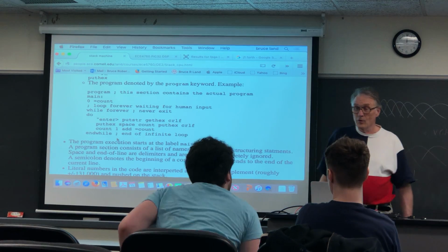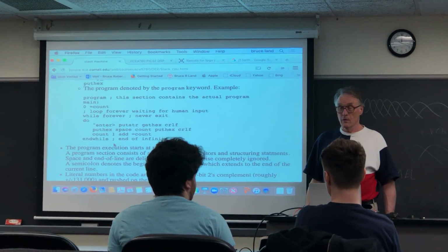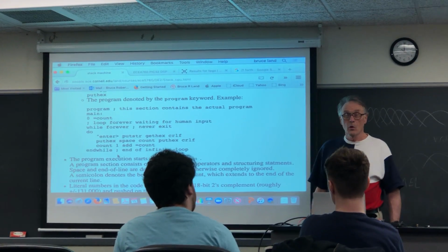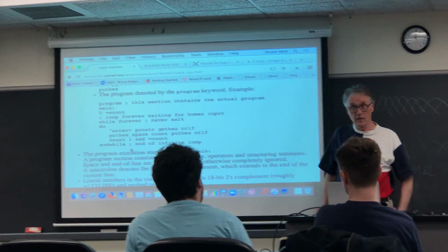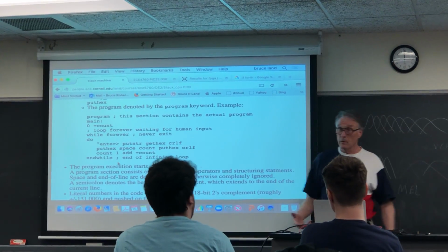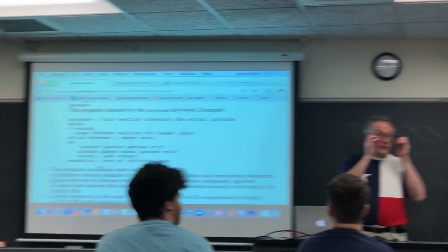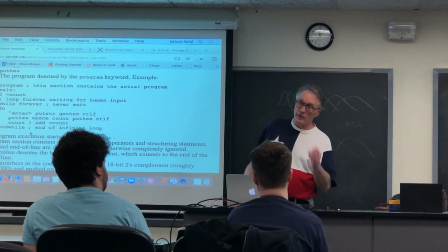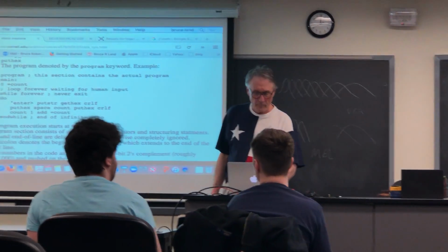Yes? So if you just want a processor, wouldn't you be better off just using the HPS, which is already there? What's the advantage of implementing this in the FPGA? So the advantage is you can build a ton of these little things. If you need an array of, say, CPUs to do, say, a drum, or a Mandelbrot set, you can write CPUs all over the place. They're small, and therefore they are fast. So how many of these things can you get on that FPGA?